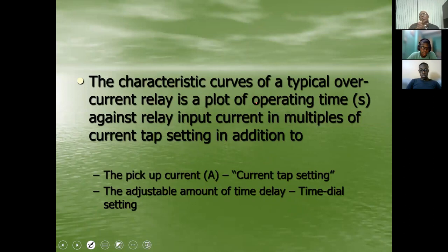All right, so let's look now at the characteristic curves of your relays, okay? And note, it is a plot of your operating time versus multiples of tap, which again, you are familiar with. Good?